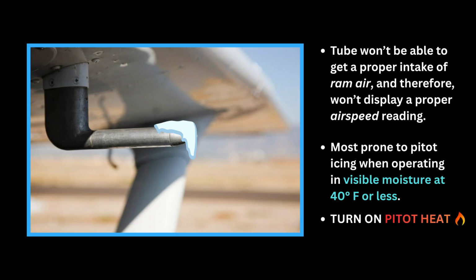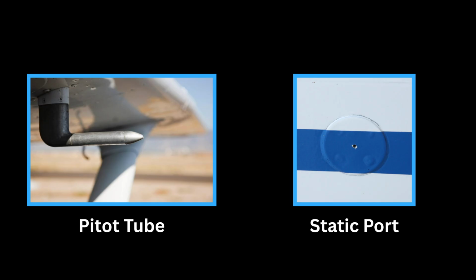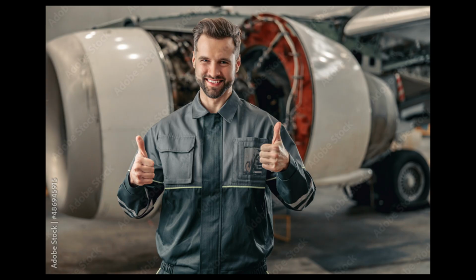Regardless of whether or not you notice icing, if you're in these conditions, turn on your pitot heating. As far as blockages go, both the static port and the pitot tube can be affected. Blocking in the pitot tube or static port can be caused by icing, insects, dirt, or tape left on during maintenance, in which case you know it's time to get a new maintenance guy.